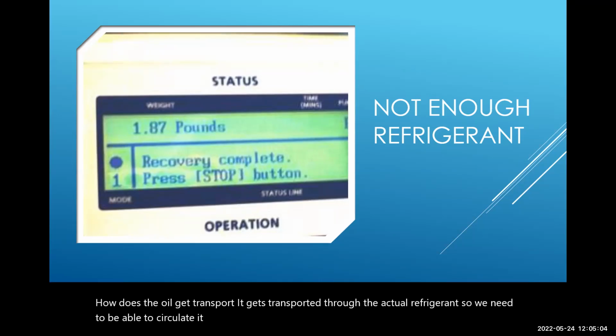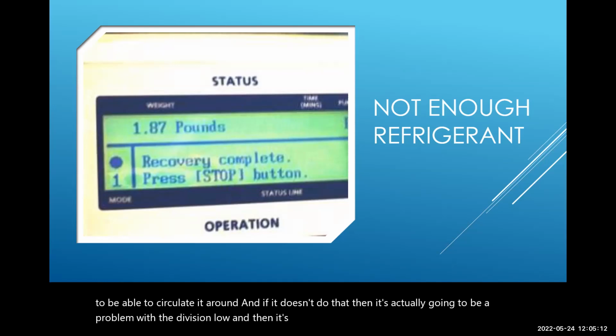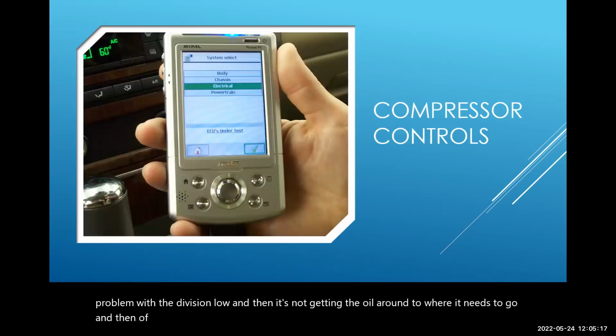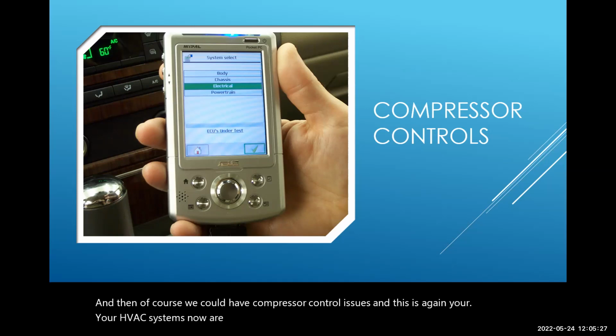If the refrigerant is low, it's not getting the oil around to where it needs to go. And then, of course, we can have compressor control issues. HVAC systems now are all electronic and automatic, and we could have an electrical problem that way too.